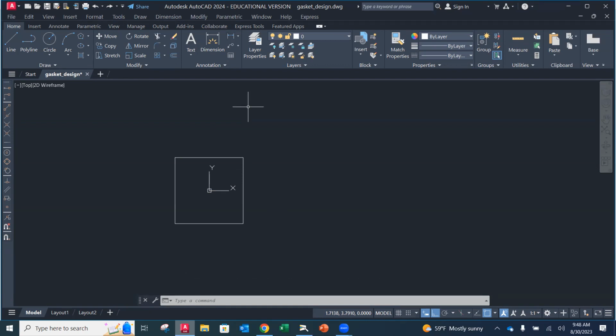So now I've got that square in place. Now, as I look at it, if I go over the top and hover, notice it's all one entity. So all 4 sides kind of light up, and I've got, if you would, a polyline around the outside. Now that's convenient, right? Because you'll notice that to create the next squares that are on the inside, I can just do an offset, and it's gonna do it for me.